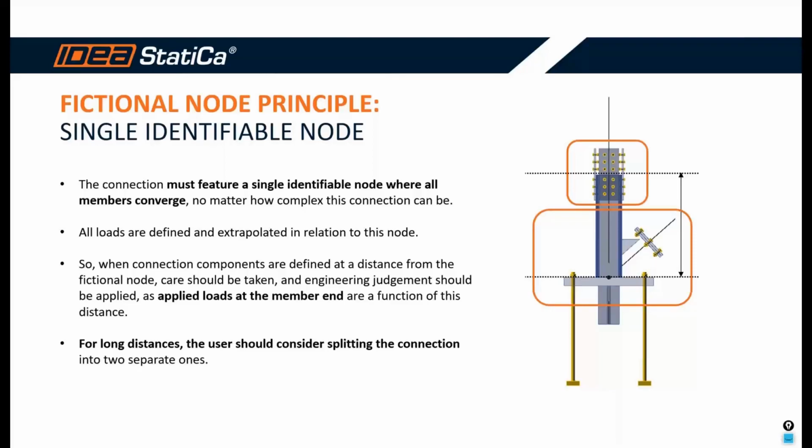Now, the stub operation does not support lap splices. It only supports end plate splices, like in the picture you see at the right. Now, in order to achieve the result that the user wanted, we need to use a stiffening member for the definition of the stub.